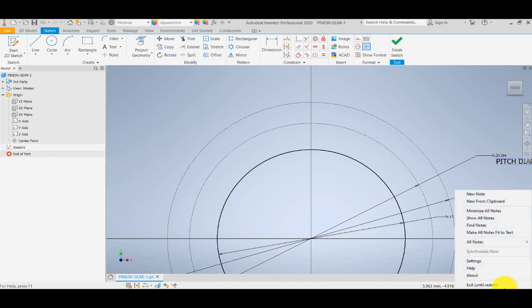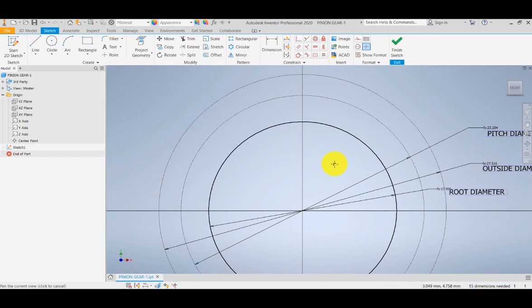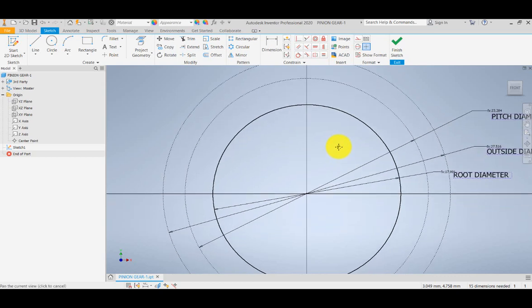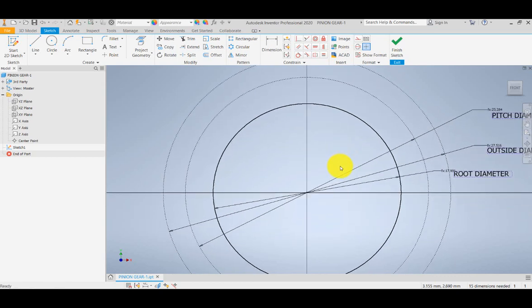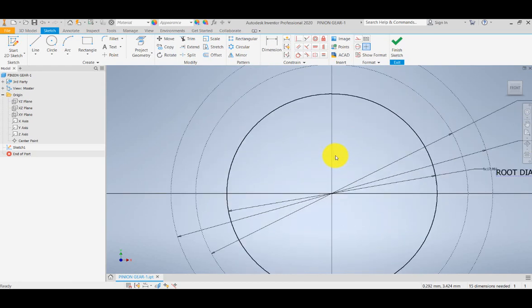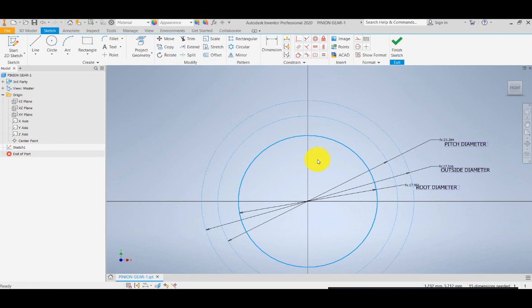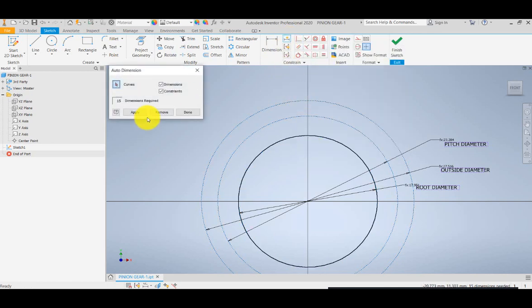Okay, so for my circular thickness, I will be drawing a line. So take my line here, on the center of my circle, I will draw a line here. And I want to check this one as a broken line, so this will serve as only my guide. Okay. So please escape. Then I'm gonna give a distance for this one, or angle. So not a distance but an angle. You will notice here I don't have the reference, but I will be highlighting my y-axis and make it visible so that it will serve as my reference. So make this one also a hidden line.